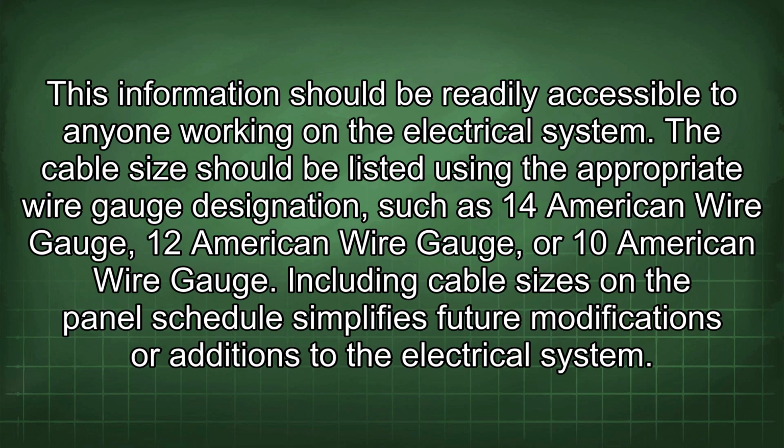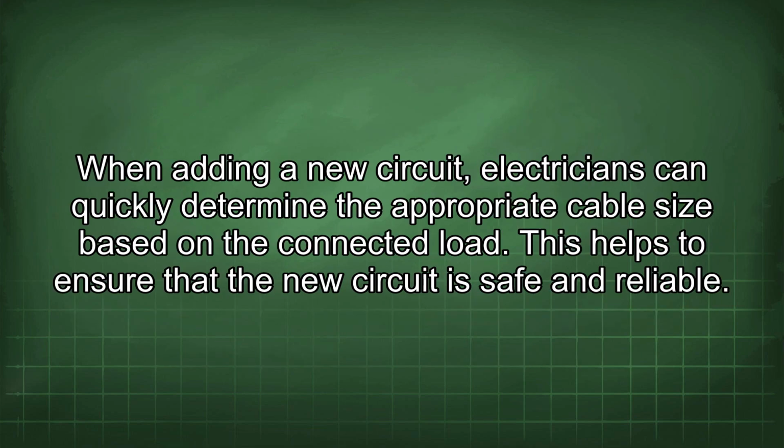Including cable sizes on the panel schedule simplifies future modifications or additions to the electrical system. When adding a new circuit, electricians can quickly determine the appropriate cable size based on the connected load. This helps to ensure that the new circuit is safe and reliable.